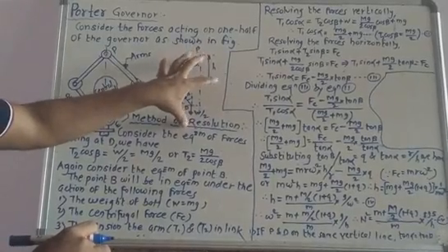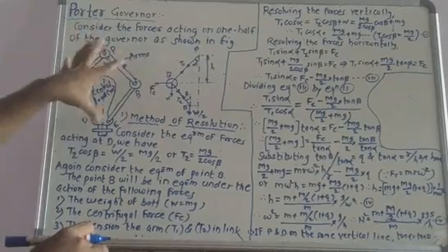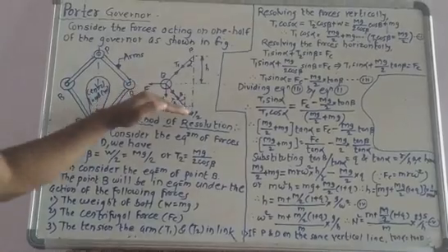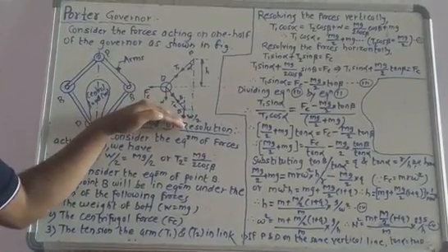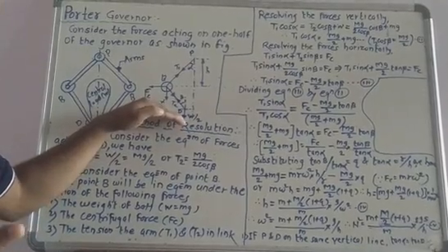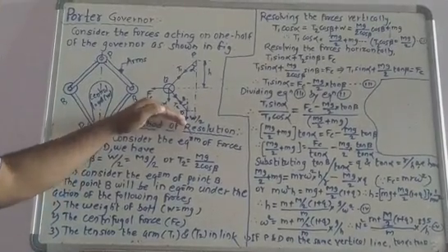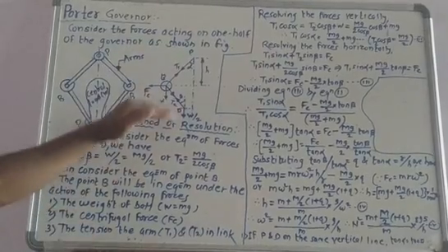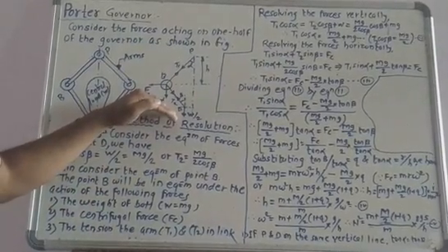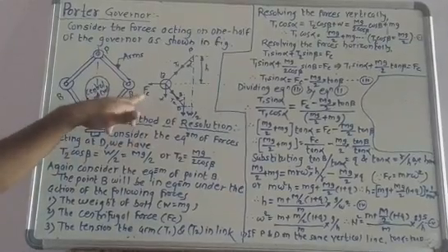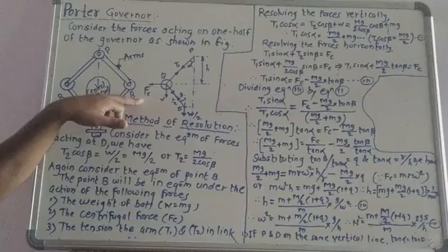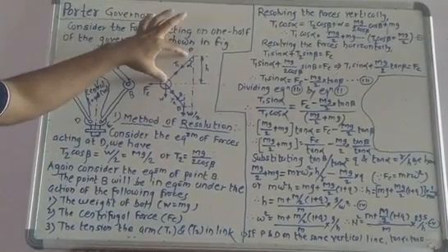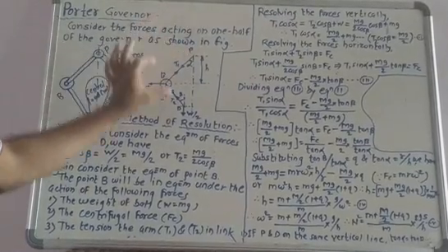So this indicates the free-body diagram of this configuration diagram. As per our earlier discussion in case of Watt governor, the various notations we have used: let m indicate the mass of the fly ball, so w is nothing but the weight of that fly ball. Fc indicates the centrifugal force acting on this ball. T1 is the tension in the arm.